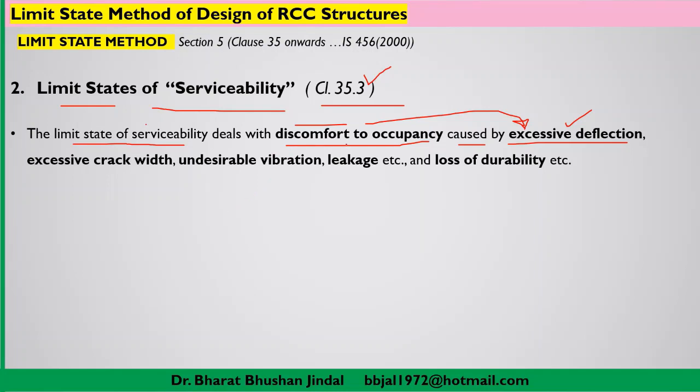So what type of discomfort? It may be due to excessive deflection. There may be excessive crack width. If you find cracks in any type of structure, say a slab, you will try to move away from the slab because you will be losing confidence. Any undesirable type of vibration, leakage, etc., or loss of durability. So this will be the limit state of serviceability when you feel any type of discomfort.